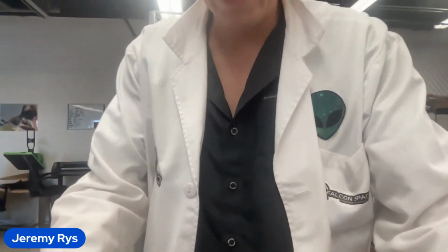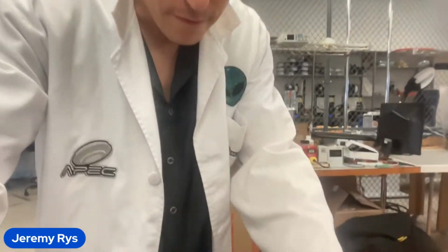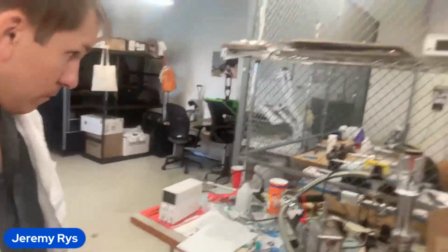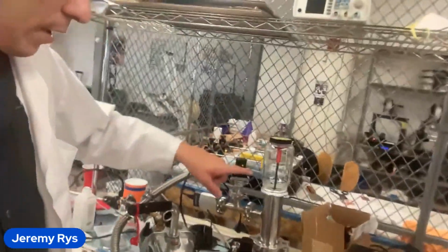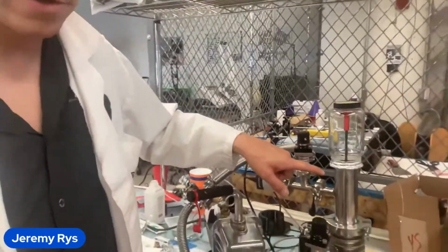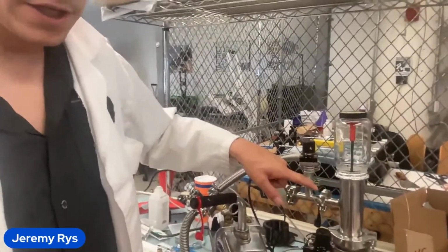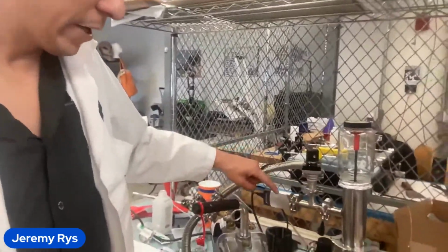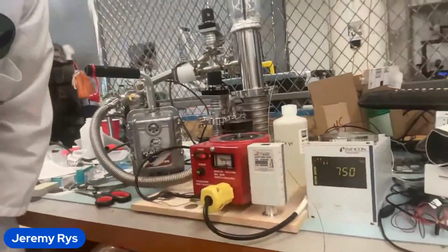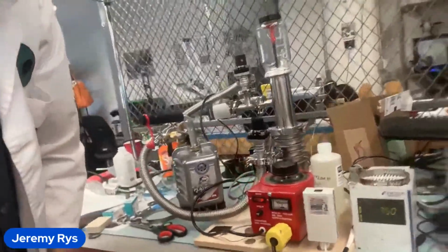So next, since Curtis Horn is here with us in the audience, we'll use this opportunity to show off our demonstrations of the Charles Buhler machine. Right now we have a glass bell jar. I just used a mason jar with some vacuum epoxy glued to the end of a KF50 flange. Out of there comes our vacuum sensor, which is connected to this machine right here. It shows 750 torr. That's atmospheric pressure right now.